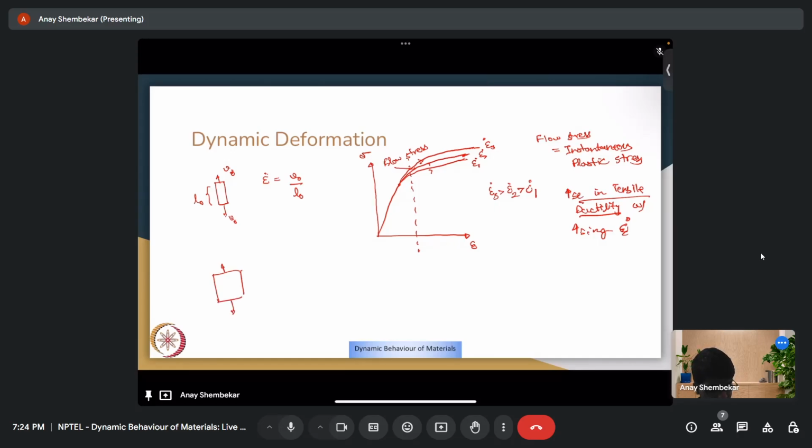And we also saw that for a dynamic loading case, suppose I have a material like this and some stress sigma is applied, then for the quasi-static case, and this is the dynamic case, for the quasi-static case you see a single crack going throughout, which is how we know the material fails, whereas for the dynamic case crack branching is seen, and that branching only happens at some velocity v greater than the critical velocity for crack propagation.